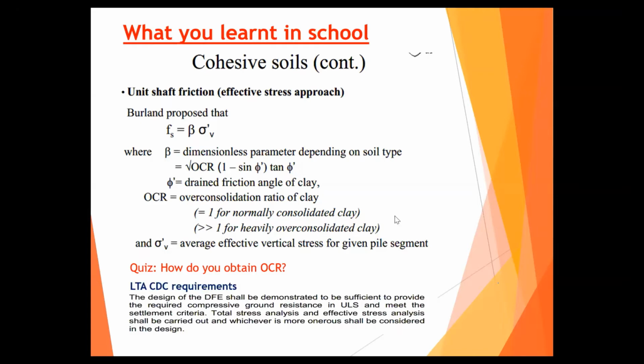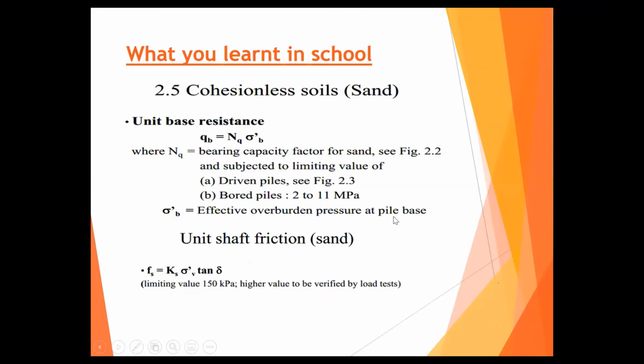Okay, move on. Now, cohesionless means sand. There is also a bearing capacity factor for sand. You can check the figure. There are some numbers recommended. So for bored piles it is 2 to 11.